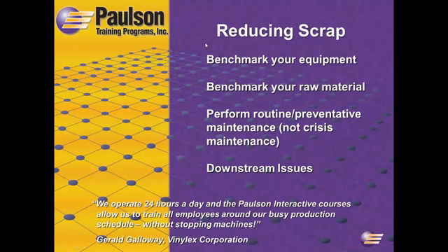So my recommendations, getting near the end here, are to benchmark your equipment. And again, I'll use that word calibrate. Your machine, just like a car, came out of the factory with a certain set of specs that it could maintain. There's no reason that those shouldn't be still good a year or 2 or 3 down the road. Sure, screws don't last forever. They need to be pulled, replaced, cleaned, maintained. Molds don't last forever. That's part of the ball game, and there's no way around it.